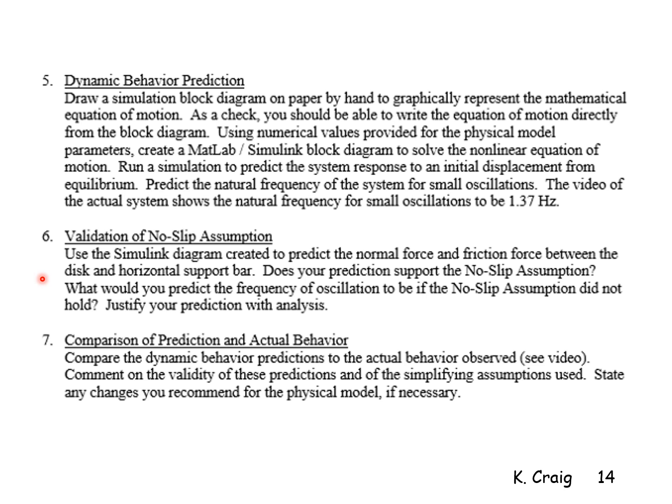The coefficient of friction is the ratio between the friction force and the normal force at that point of contact. From my simulation, I can determine what that ratio is, what the coefficient of friction needs to be throughout its motion to support the no-slip condition. If that coefficient of friction is less than or equal to the actual friction available in steel-on-steel contact, my no-slip condition has been validated.